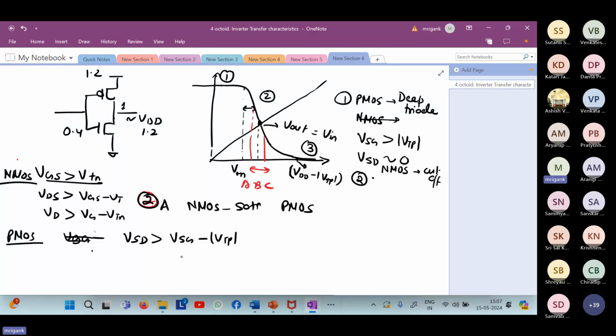So remember, how do we remember the condition for NMOS, PMOS? The pinch off concept, so that you can recall so that there is no confusion. For an NMOS, the pinch off occurs when you have the channel region getting clipped at the drain side. Suppose this is the drain region, you have a gate voltage over here, and you are having source potential on the other side.